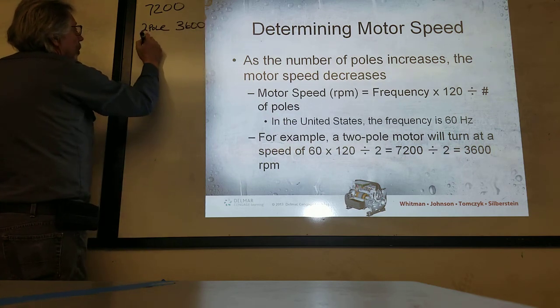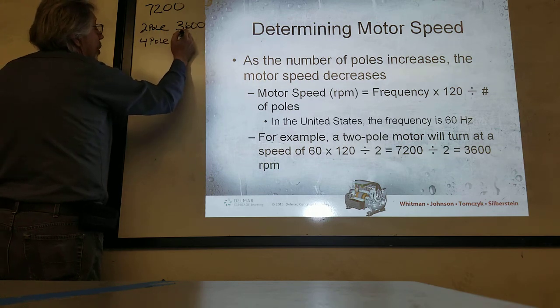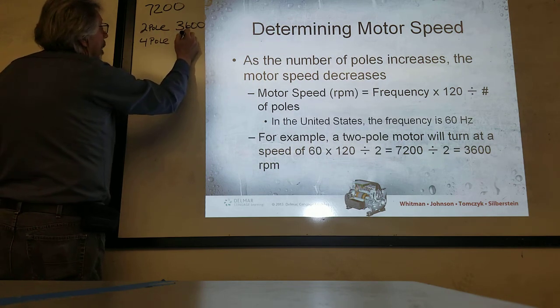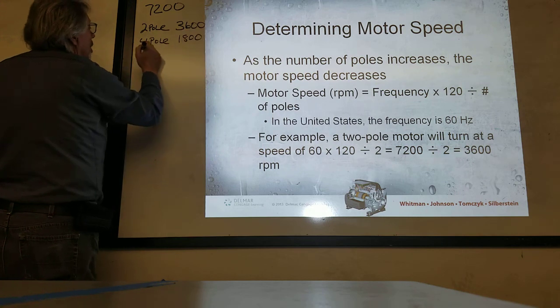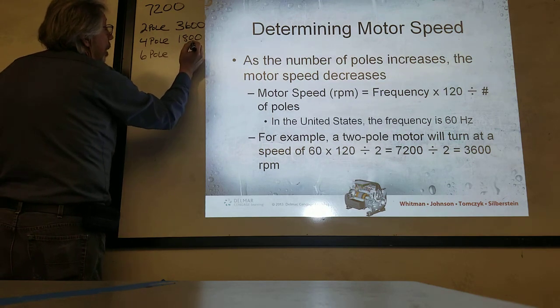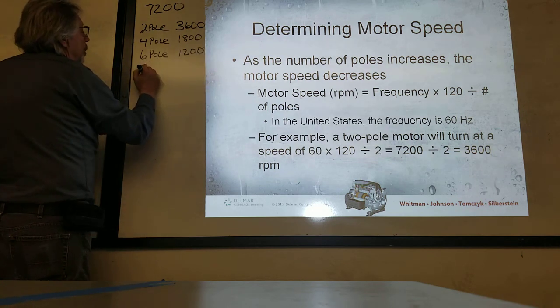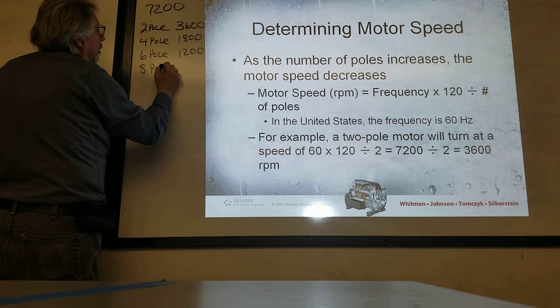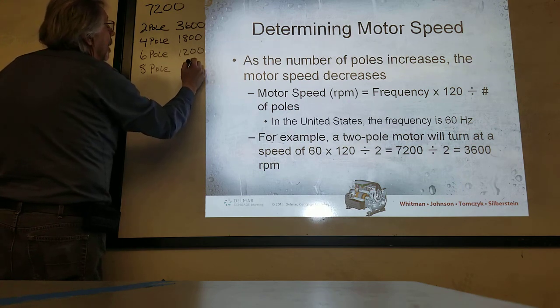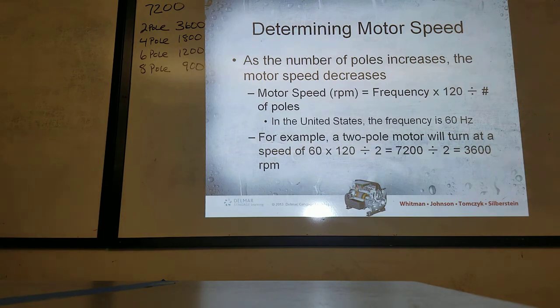If you have a 4-pole motor, it's gonna be 1,800. 6-pole, 1,200. 8-pole, 900. Okay, got that? Good.